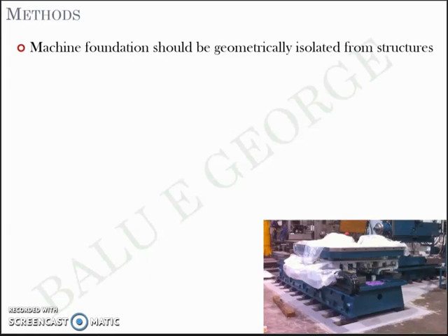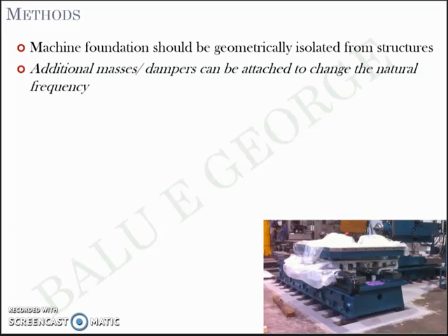The machine foundation should be geometrically isolated from the structures, which means it should be kept at a certain distance, ensuring that the vibratory waves don't affect it. So geometrically you can isolate it. Or you can have additional masses or dampers attached to change the natural frequency.